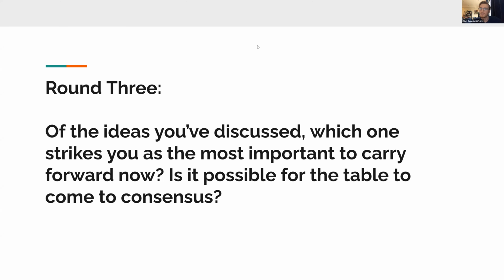Some of the things that we talked about were adding in power per volume for the bioreactor, the mixing time and the KLA constants, as well as the VVM, which I guess is a flow of gases volume per volume of bioreactor metric, and the tip speed. Those are all important parameters, and especially power per volume can inform scale up, I guess.